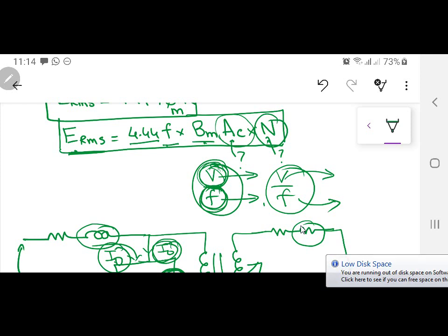अब मिसाल के तौर पर एक छोटा सा question है which I also asked in the last class also. I have a shell type transformer here, ठीक है। मैं इसको जरा move नहीं कर सकता because ये आपकी VGA की cable खराब है, मैंने इसको रखा हुआ है इस तरफ से। If you see on this side, this is one set of wire coming out, one pair, and on this side you can see there are different taps coming out. Now just by seeing this transformer, can you tell me which one is the low voltage side, which one is the high voltage side? This one is low voltage.